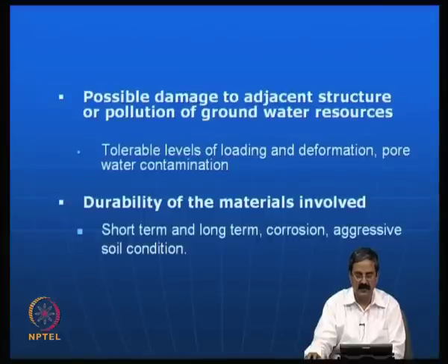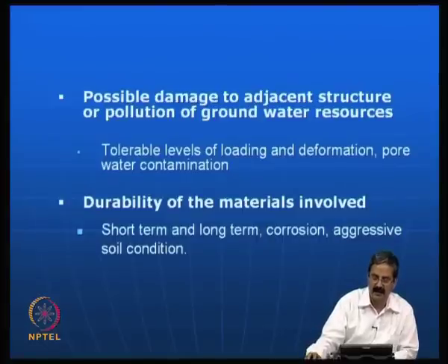Then there are some materials which will have corrosion. Say for example, in places like Bombay, because of the sea intrusion and all that, people say that they do not want to use steel, they would like to have PVC coated materials like that. So, aggressive soil conditions are another important problem, because finally whatever ground improvement technique you are using, say for example, you are putting some reinforcement, the reinforcement should be working for about 30-40 years or 50 years. If the reinforcement is dissolved because of the aggressive soil conditions or some other problems, or somebody removes it, then it is a serious issue.